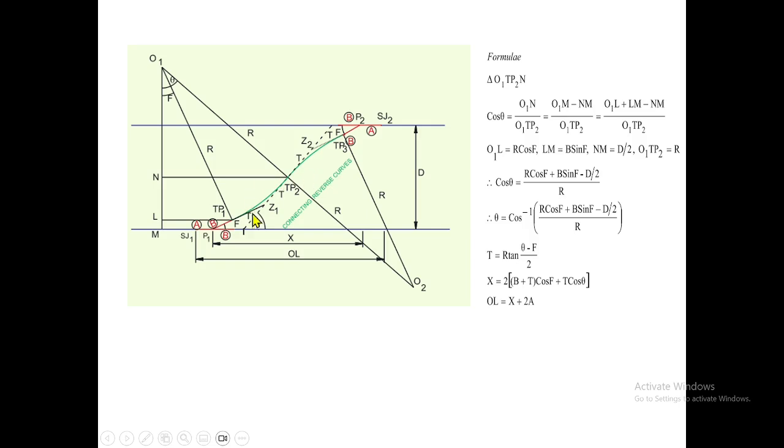So this is a detailed drawing of this connection. Here we are using the same angle of crossing, and the radius is also the same. Similar to the connection, you have to solve the trigonometry for the deflection angle: the deflection of this curve and the deflection of this curve. So this is theta. Since this is a deflection angle, when you are keeping it, theta minus phi will be this one.